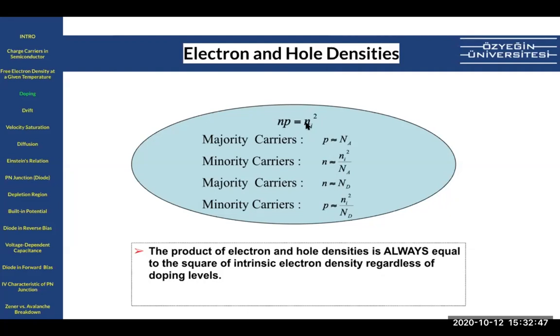And so let's say I give you the number of Ni. I tell you it's silicon and it has this much Ni at this much temperature, and I tell you I dope the silicon structure with n number of phosphorus, and that number of phosphorus becomes the number of electrons, because we are doping it with a lot of atoms that will provide the same number of electrons.